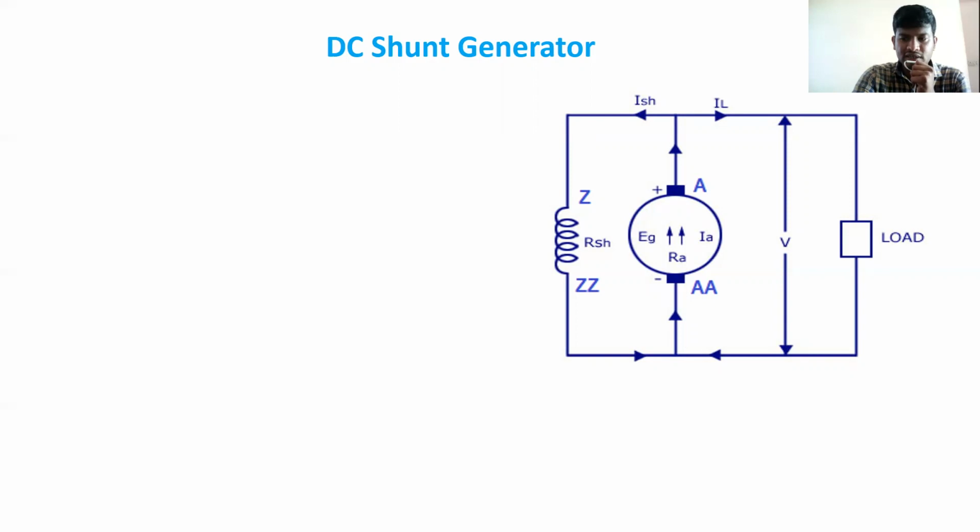That means practically there is no supply, the generator is not working. But even without any current, there is some flux passing through the windings. Due to that flux, the generator can develop some minimum amount of current. That current can energize the field winding, which increases the flux lines in the circuit. So the armature current can energize the field. That means it is excited by itself, so it is a self-excited machine.